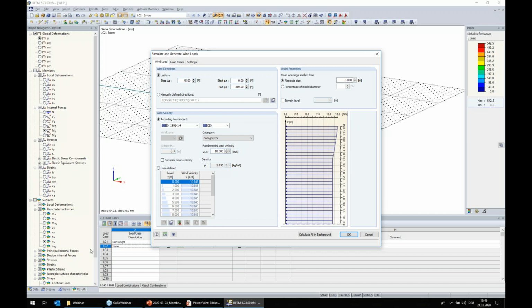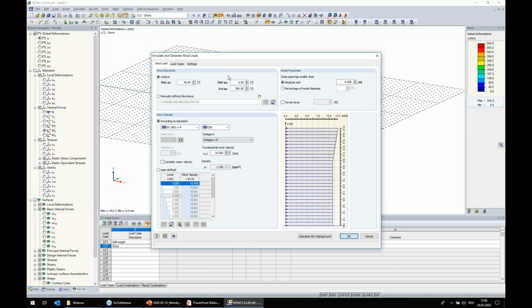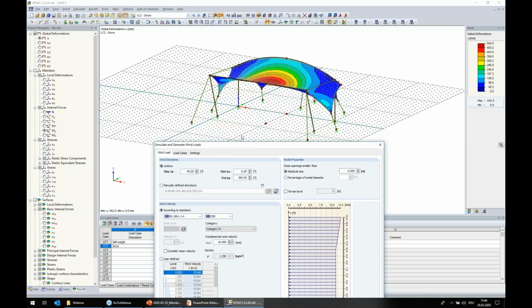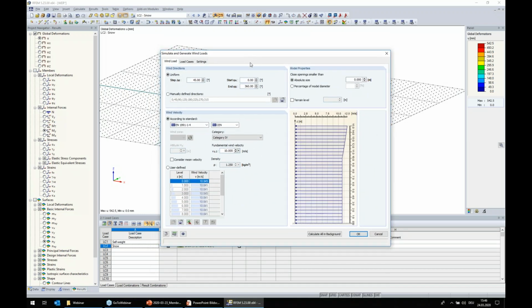At least it takes this model which is given in the background, but also the information about the wind flow for which it should be considered. And here we have to define, of course, the wind directions. The wind directions are defined in this first block. We can say every 10 degrees increment we want to check it, but imagine this results in a lot of load cases.